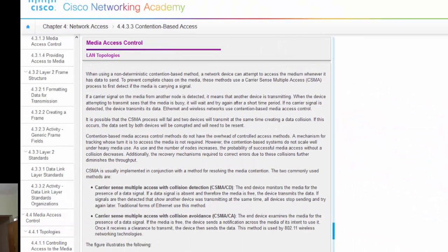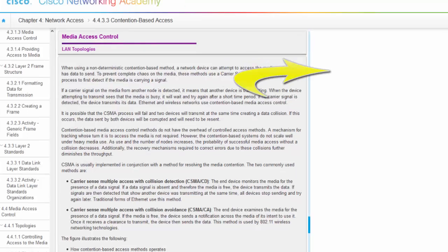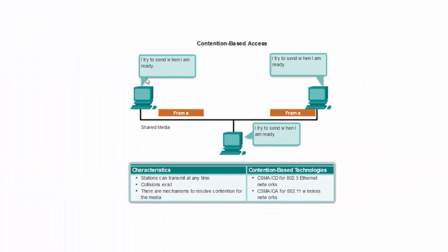We use some kind of a carrier sense multiple access technique, and the way that this technique works is that each node, before it tries to send anything on the line, actually listens to see if there is any transmission currently happening on the line. And that can be detected easily using some measurement of the energy on the line. So if the energy on the line is high, this means that someone else is transmitting. In that case, this node will abstain from transmitting over the shared line.